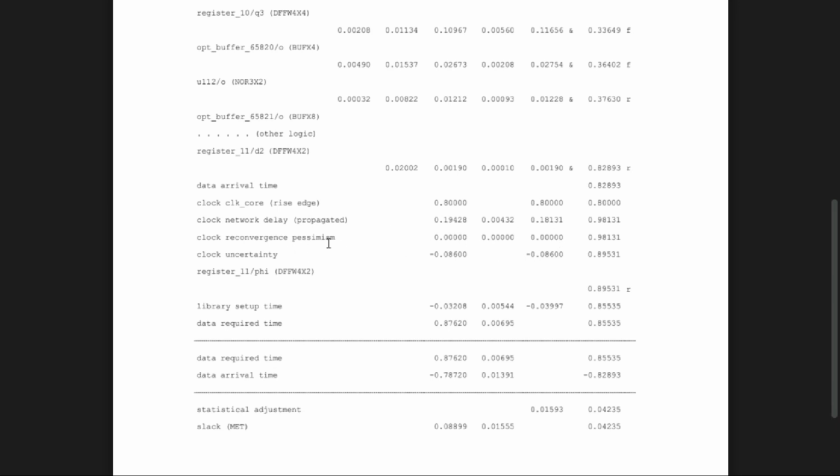All right. So also there is something called clock uncertainty. This uncertainty is defined for some additional things which we don't have any control over, right? For example, clock jitter, or in some cases we don't know how the waveform of the clock will be for certain advanced nodes.